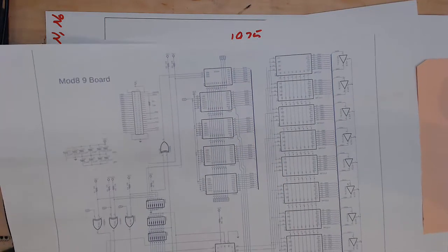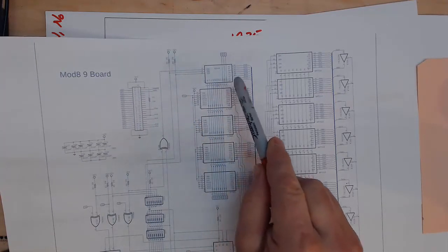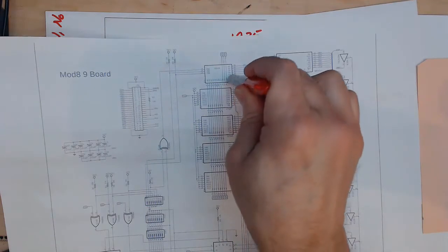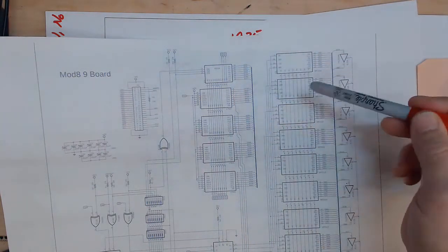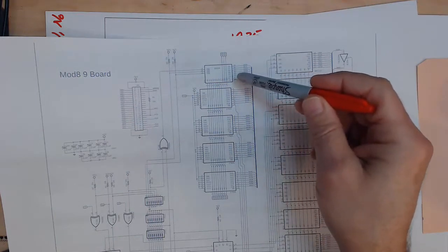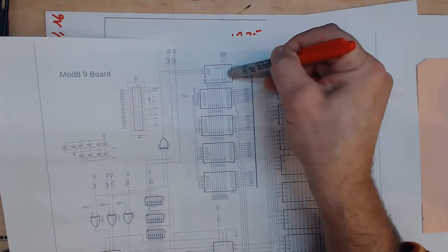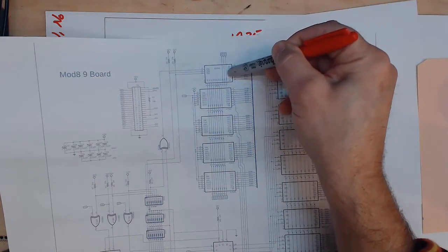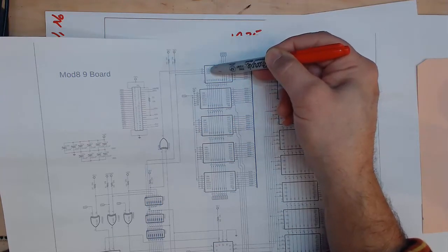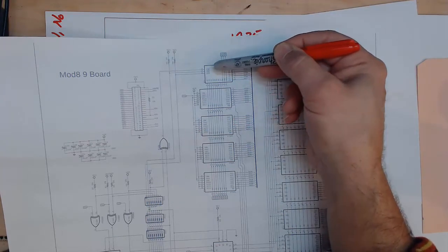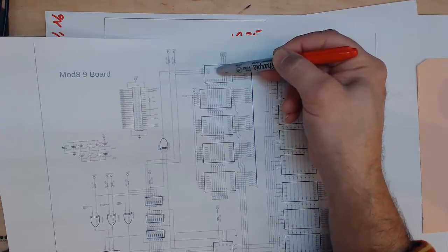So now you can see why we had to have some additional logic to select that chip, because when the manufacturer got that chip, let's say they were putting out a system monitor, a resident monitor, or they were putting out a bunch of games or something, and if they had a card that could have 8 of these 8316As, you could populate that with 8 different games as long as each of those had a different chip select, and they would all be on the same card. There would be no decoding because these chips would individually know when they were being addressed.